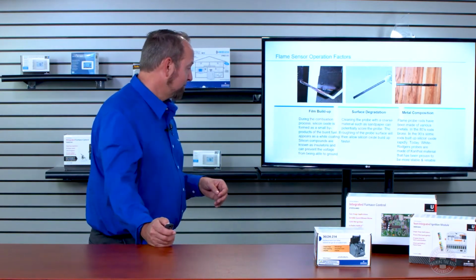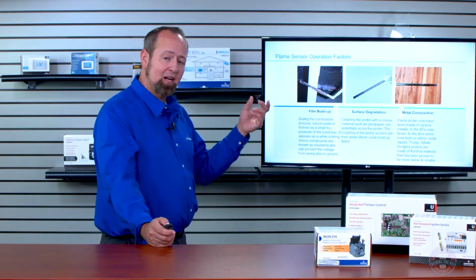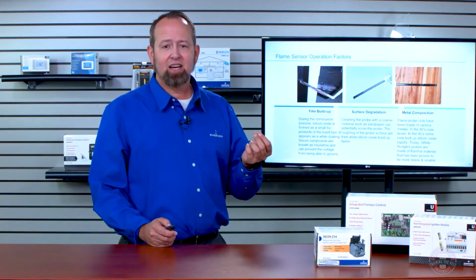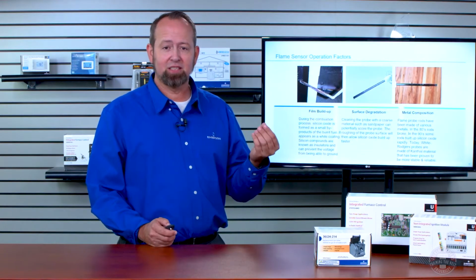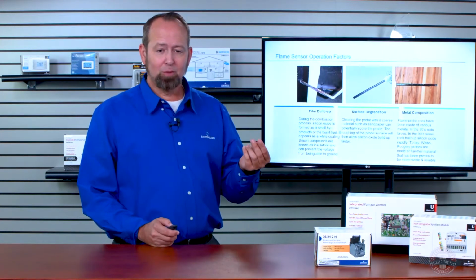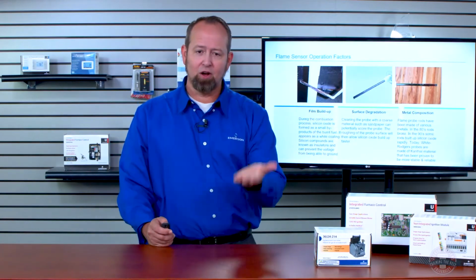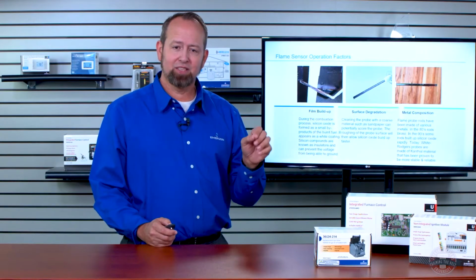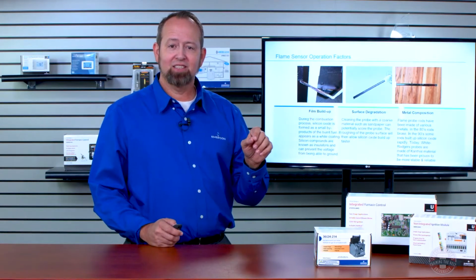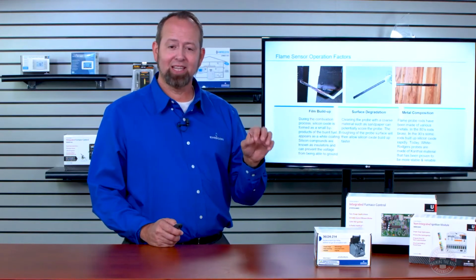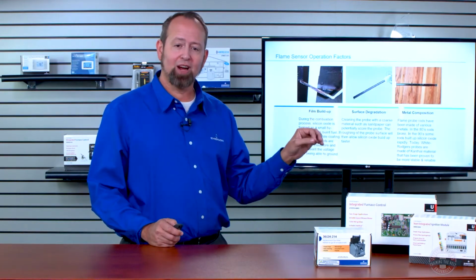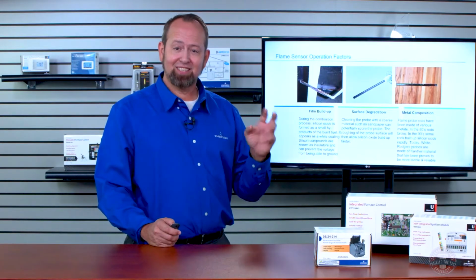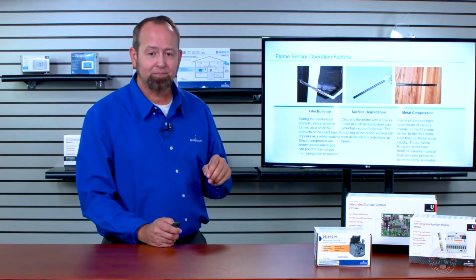It's a very simple product on the probe. It's something that's not hard to get off. It's not anything that takes a lot of effort. It's a really light film. It's almost like a light dust that you could just wipe your hand off and pick the dust up. That's how light and easy it is. However, because of its compound properties, it acts as an insulator and will insulate that signal going to ground and not allow the furnace or the control board to see that DC signal going back to it.